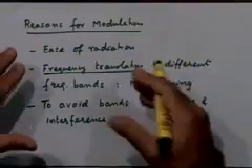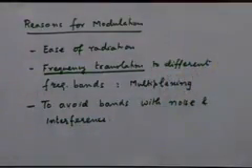Basically, think of modulation as a frequency translation operation. If you carry out some frequency translation operation and you find that in that particular band there is a lot of noise, a lot of interference coming from some other place, you would like to modify it, right? So it allows you to choose what band you should use so that you are not susceptible to noise or interference if it is frequency dependent. So these are some of the reasons for using modulation, right?